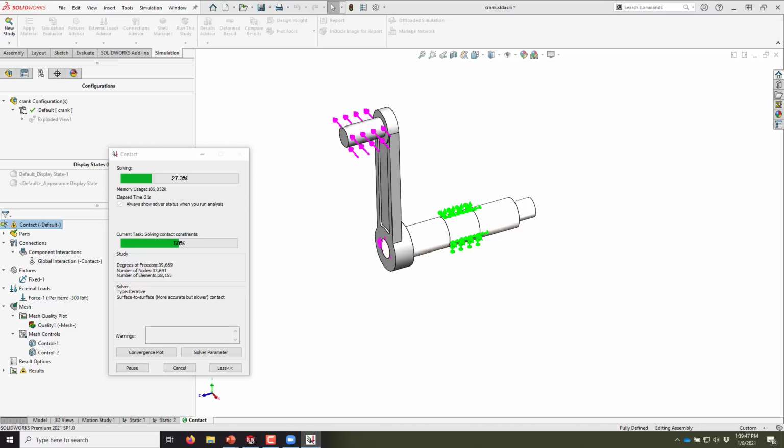Quick question: does SOLIDWORKS have a polyhedral mesh option? No, not in our meshers. A lot of CAD-based simulation tools, we try to keep it really simple so that the designer and the engineer doesn't have to worry about creating this type of mesh, that type of mesh. Okay, we try to keep it really simple. The only elements that we use, for solids anyway, are pretty much tetrahedrons.